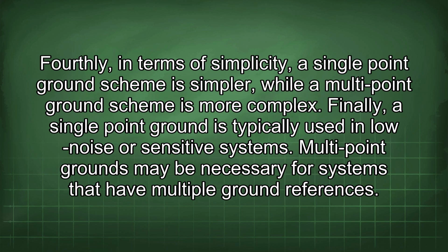Fourthly, in terms of simplicity, a single point ground scheme is simpler, while a multi-point ground scheme is more complex. Finally, a single point ground is typically used in low noise or sensitive systems. Multi-point grounds may be necessary for systems that have multiple ground references.